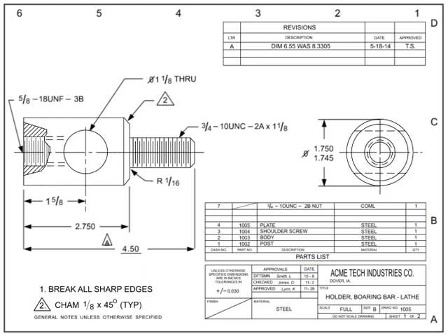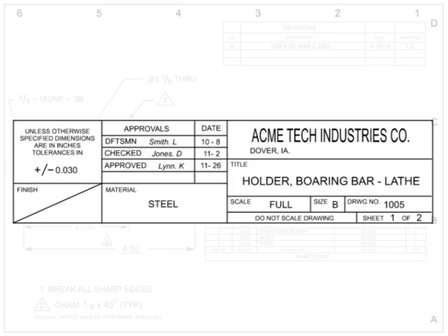The first place to look for information about a blueprint is on its title block. Most title blocks are located in the lower right-hand corner of the drawing. Although the title block information can vary by company, certain information is basic. The title block, at a minimum, contains a company's name and usually includes its logo and address. The drawing title block can also be called the noun or nomenclature. A short description of what the item depicted or the name of the part is typically located in this block.